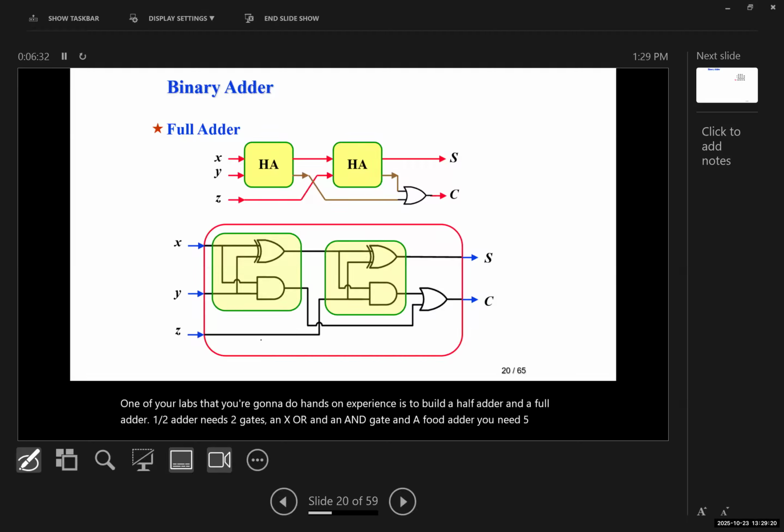Now, if X0, X1, X2 is equal to 1, 1, 0, then all of them are 0, D0, D1, D2, D3, D4, D5, but D6 is 1 and D7 is 0. So this is D6 because this is equal to 6. Okay. So D6 is 1, the rest of it is 0. Is it clear, or do you want me to